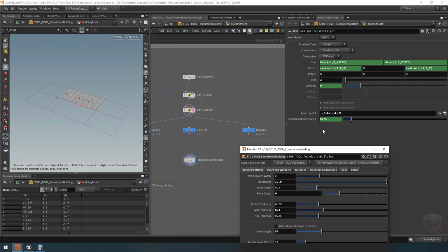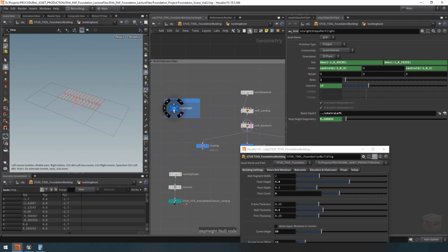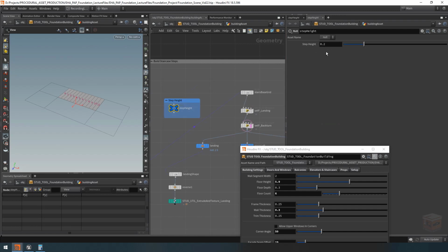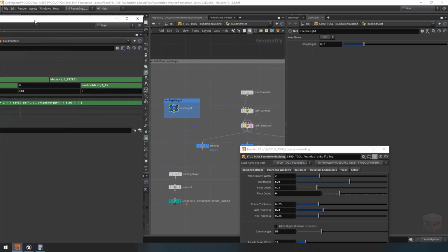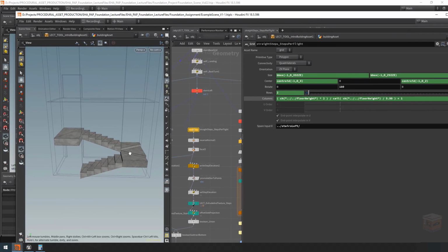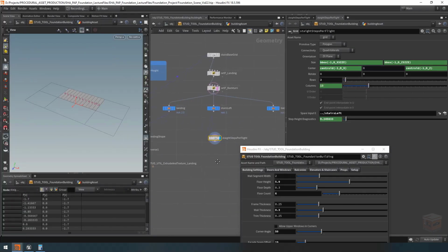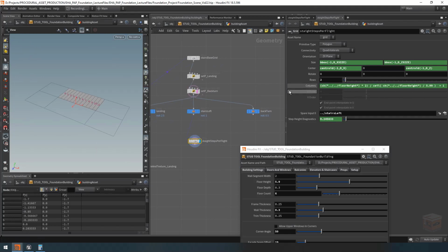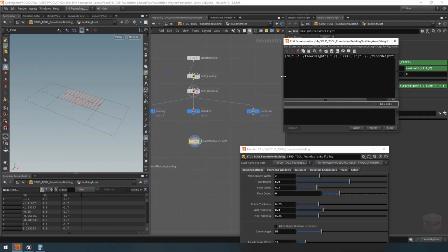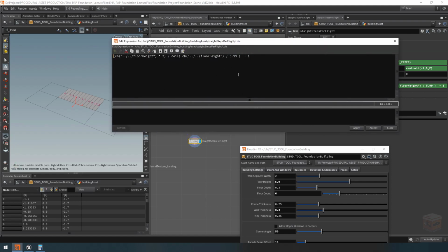Now at this point, because we're over 6, our diagnostics won't work properly anymore. But if I were to go to say 5.9, then you can see that our maximum step height in this case is going to be 0.25, which is not 0.2, but it's close enough that I'm going to give it the benefit of the doubt. Plus, we're not actually taking into account this part here, and the fact that it's going to scale slightly, so we're probably going to be closer to 0.2 than 0.25 in the end anyway. Either way, if you have this expression here set up, then this part should work properly.